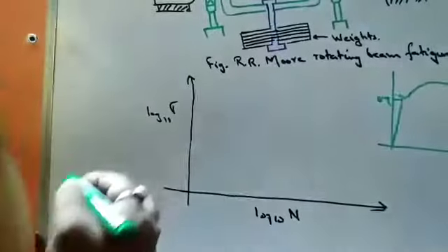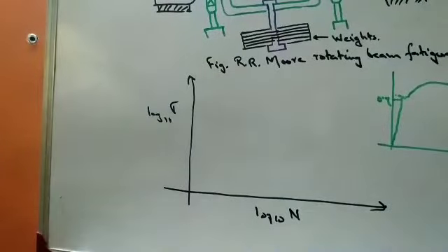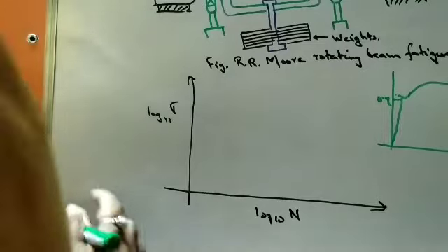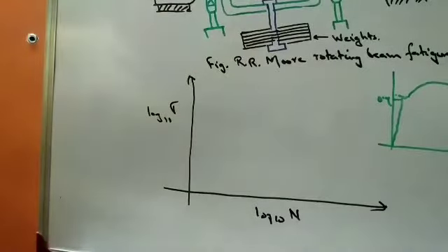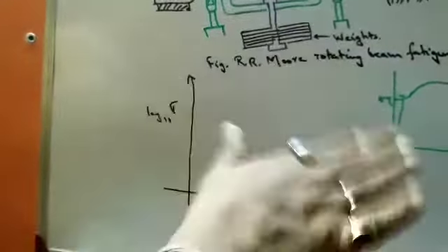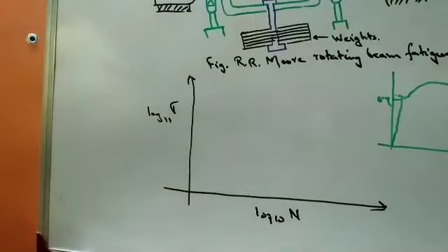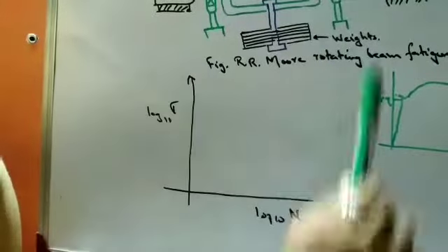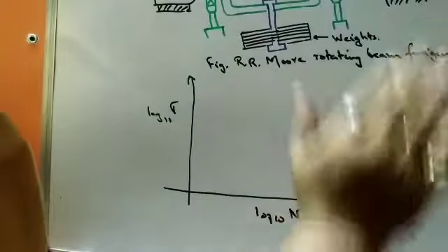If you look at the stress-strain diagram for a ductile material, suppose we try to load at 0.9 times the yield stress. For the first time, we do not cause yielding. That means we are basically doing what type of loading? We are basically doing a high cycle fatigue.